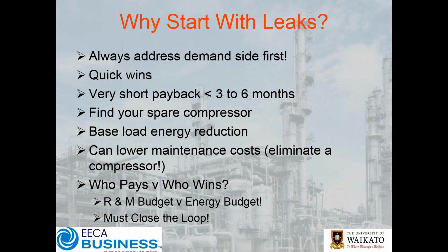On a lot of larger sites, you can find where you've got multiple compressors. It's not uncommon that when you start fixing your leaks, you actually turn whole compressors off. And so not only do you then start saving your energy, you then also start saving on your maintenance costs. Then longer term, you've got capital cost savings as well. Great thing with leaks is they're always there, so you have a base load energy reduction. Okay, can lower your maintenance costs, as I've mentioned.